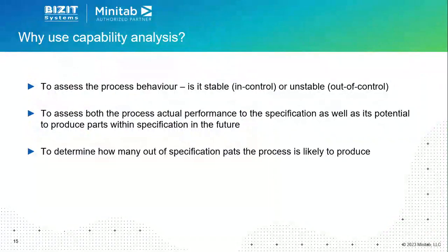Why do we need to use the capability analysis? I think most of our customers start their journey for a continuous improvement project, let's say a PDCA project or an FMEA project, all of which start with the capability analysis. When your Cp, Cpk is not capable, when you cannot achieve more than 1.33, you trigger something, and you come back to the control chart and so on.